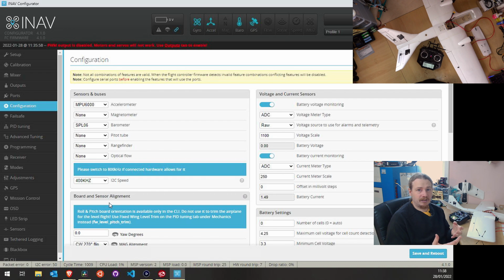This is a standard UART. You basically have something that's listening and something that's talking. So on the GPS, you have an RX and a TX, and on the flight controller, you have an RX and a TX. The TX is the transmitter, so that's talking. The RX is the receiver, so that's listening.